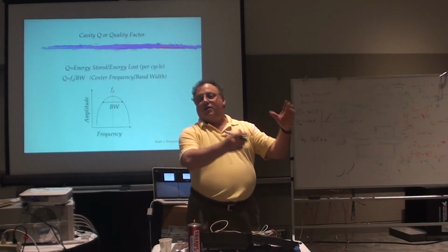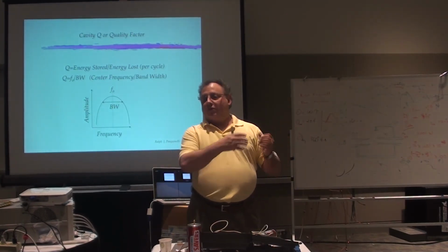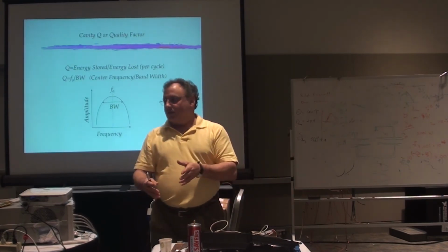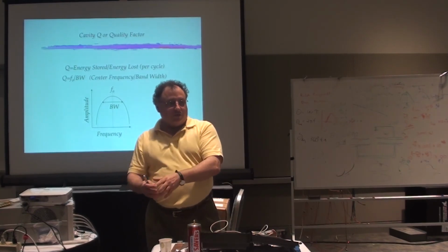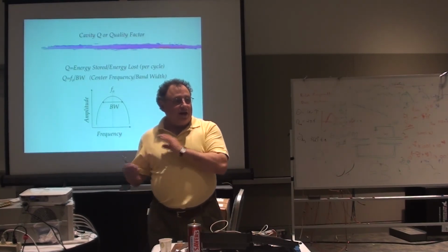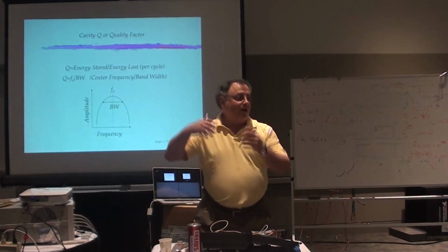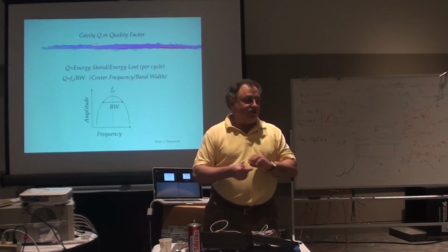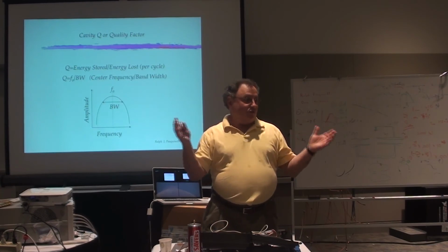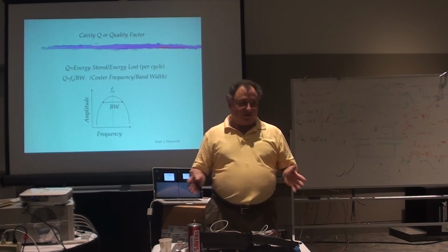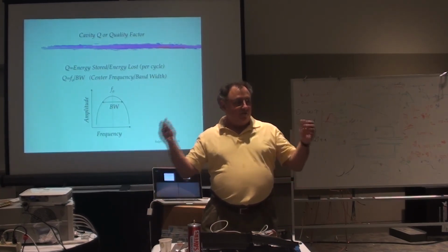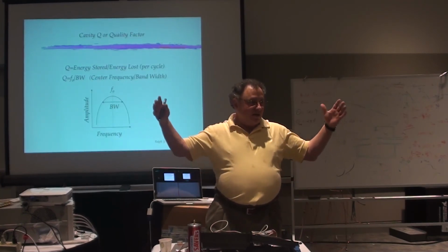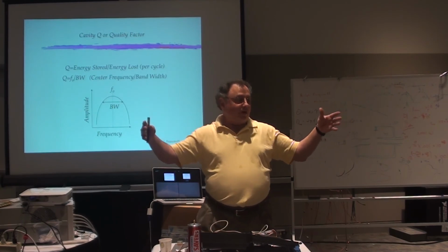So I have an amplifier now that may have several hundred ohm impedance, which needs a matching network to get to the 50 ohm transmission line. And then at the input of the 50 ohm transmission line, it goes to a coupler to the cavity, and that coupler to the cavity transforms it up to the high impedance that's across the gap. And so there's a situation where you have an amplifier, which you need to design, measure, and understand, a transmission line, matching networks, couplers, coupler variation, and you've just started. That's just the power part of an RF system.